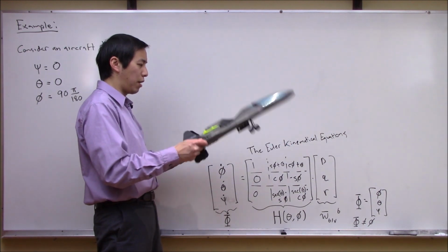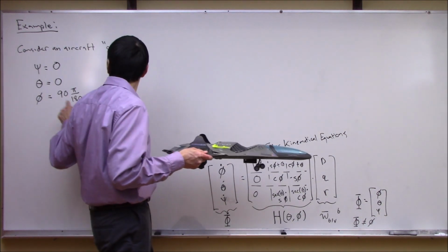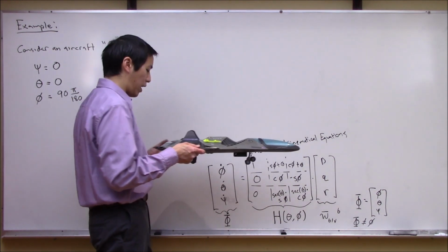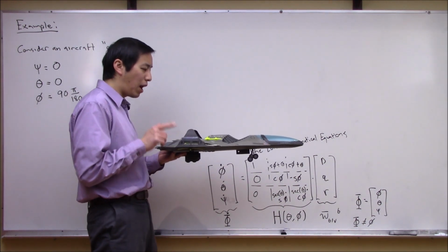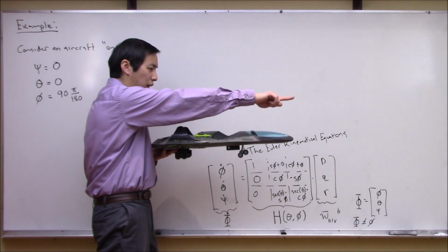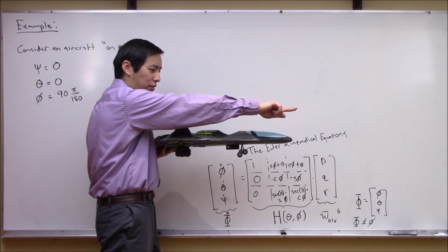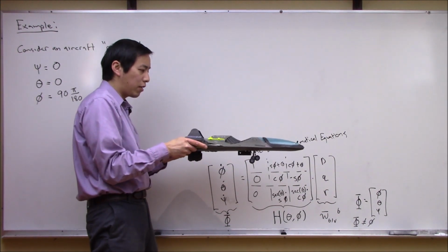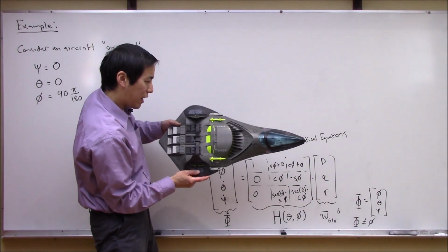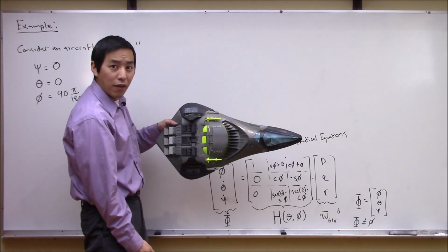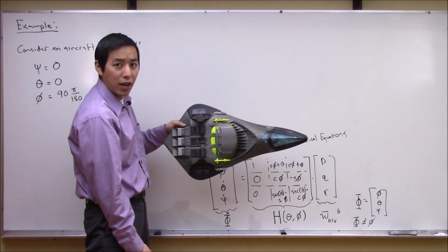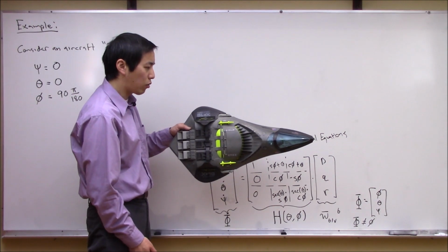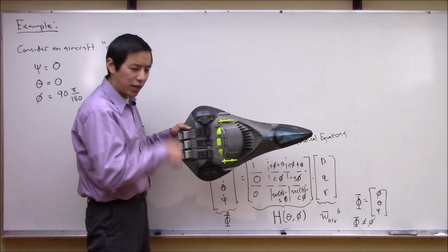So I'm not pitched up or pitched down. However, the bank angle is 90 degrees, so I have to bank this about the positive x-axis. The positive x2 frame axis is coming out, and in this case it's still aligned with north. So I orient like that. The aircraft is literally flying on its edge right now. It's just sitting at this orientation. So freeze that in your brain.